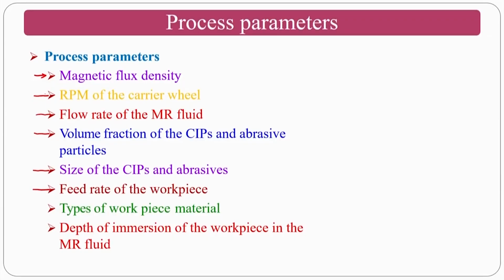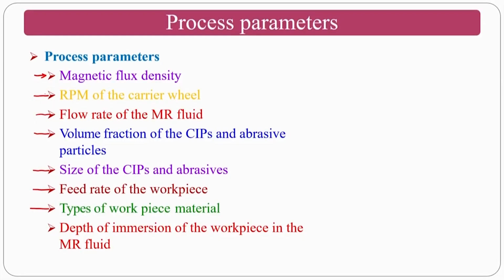For the type of workpiece material, if the workpiece material is harder, the material removal rate will be very low. If the workpiece is softer, the material removal rate will be higher. If the depth of immersion of the workpiece in the MR fluid is high, the interaction forces, or the finishing forces, will be very high.